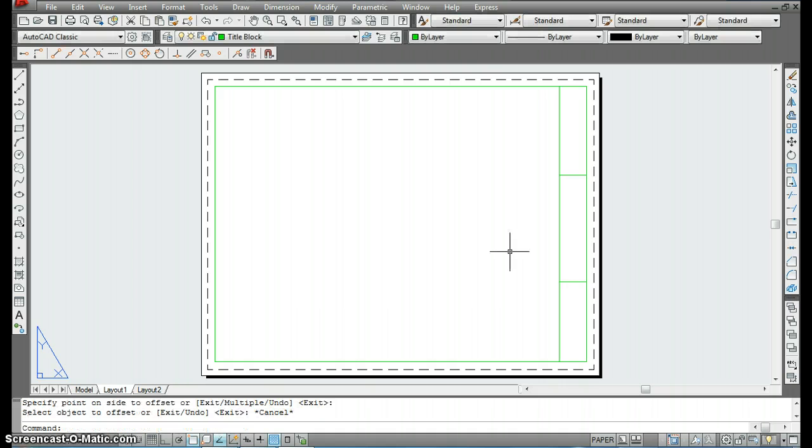So once again, get back to our offset command. The next few boxes are 0.5, just half an inch, so do 0.5, enter, click 1 down, 2 down, 3 down, and that should leave us with a little larger box at the bottom. That'll actually be a 0.75 if everything turned out right.